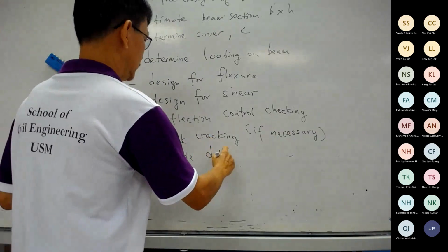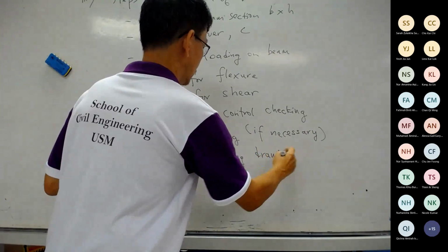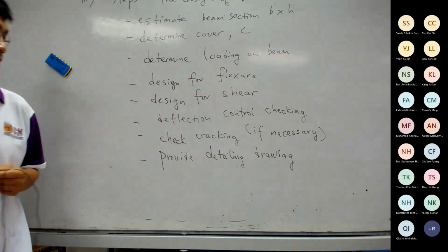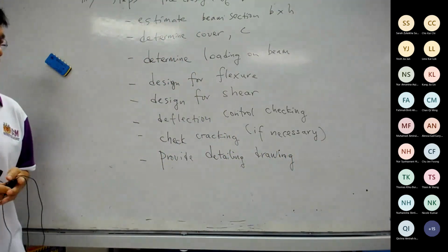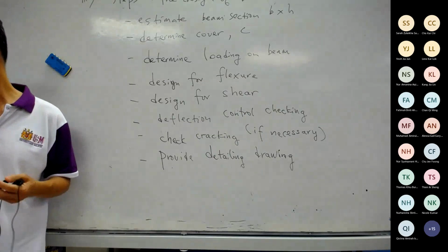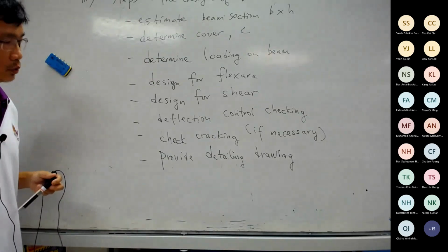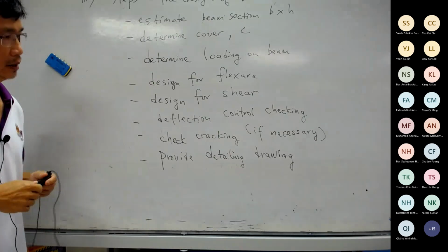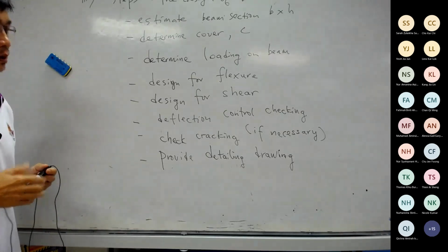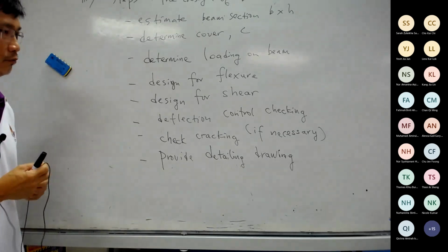detailing drawing, okay? Detailing drawings where you make it clear what is the beam size to be used and how many of them, whether it is close to the top of the beam section or close to the bottom of the beam sections, and also some of the curtailment rules, because a bar does not have to be provided, for example, those at the midspan is only required at the location where the bending moment is maximum that we design for. As it goes toward the support, then the number of bars can be reduced. So those are curtailments. Those are rules that we can follow.